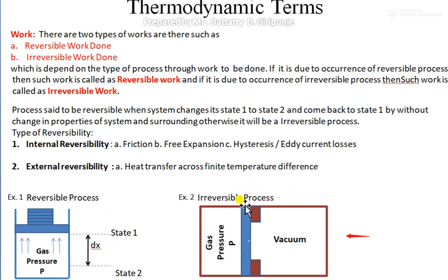If without friction I apply 10 kilonewton of force to push that piston to the initial state, then with friction I have to use 20 kilonewton, where the extra 10 kilonewton gets wasted overcoming the frictional losses between the piston and cylinder assembly.